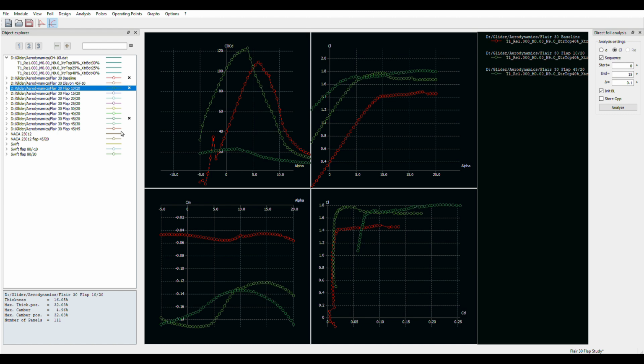And there's that data. Oh, look, here's what I was looking to find all along. This data here, lower right curve, the lighter green, that's with the flap being only 10% of chord and not 45% of chord. And look, we keep the nice low drag, and we get a nice bump up in the lift up to almost 1.8, rounds over reasonably well, without all the attendant drag that you got from having it hinged way up at 45%.